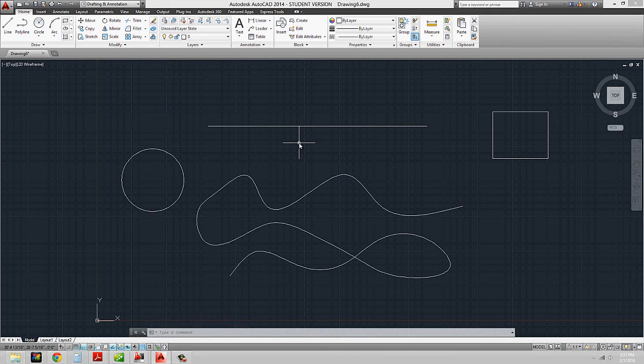That's the problem. So what it does, and the way that AutoCAD works with the divide tool, is if I click on the line, you'll see that the line is still continuous. It's still one solid line. It's still one continuous line. It's not broken up. But what the divide tool does is it essentially sits on the line, these demarcation points of where these points of separation are, these points of division are. The problem with AutoCAD is that you can't see them, okay, because the default is for them to be really, really, really small, like basically a point on the line.